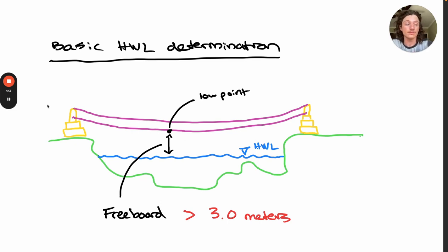course. Now, as you learned in the basic design course, all sites are treated as gorges with a 3-meter required freeboard until proven otherwise. This is a conservative assumption, especially with the effects of climate change making real impacts each year. Now, if the site seems infeasible with 3 meters of freeboard, you want to consider the following before lowering the freeboard requirement.